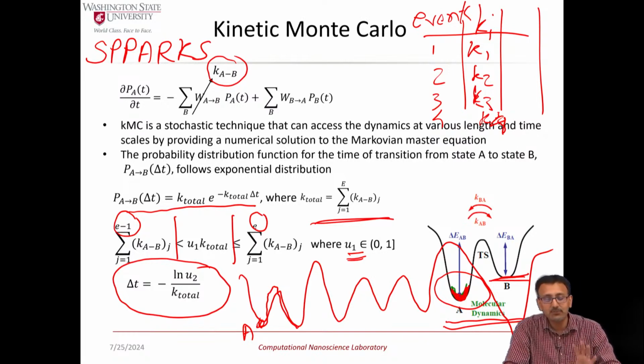Other capabilities that we have not yet added to this, and you might be thinking of, is diffusion. When these particles deposit at a certain site, do they diffuse within the surface? For certain systems, that will certainly happen. With the PCBM attachments, we have calculated the energy barrier for it. I am not presenting it here. We have a published paper which looks at the binding energy for these molecules with the perovskite. It's pretty high, so it doesn't really diffuse. We have also looked at surface diffusion. Surface diffusion is pretty rare for this system, but if you're looking at other sorts of deposition processes, that will be an event that you have to model.